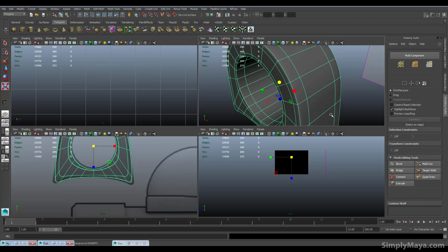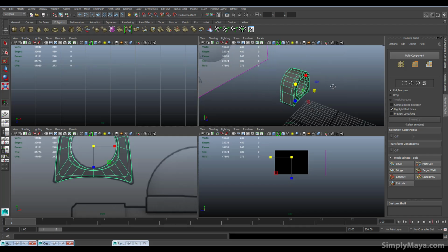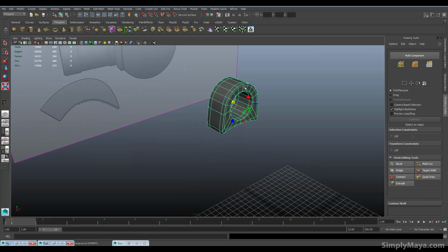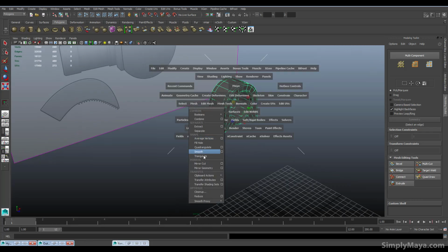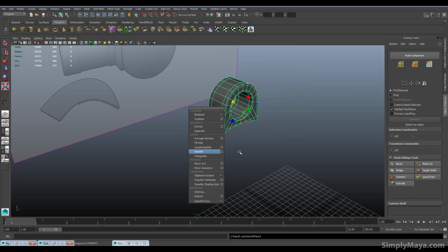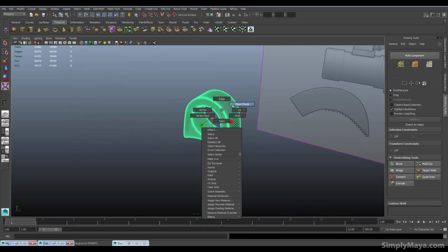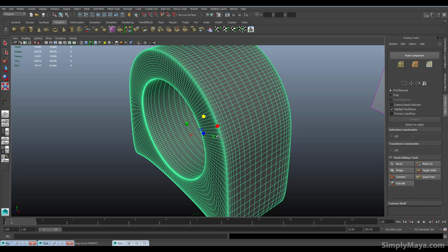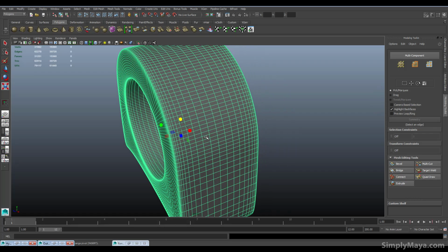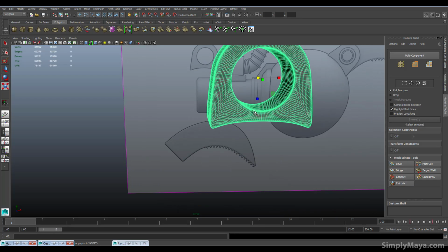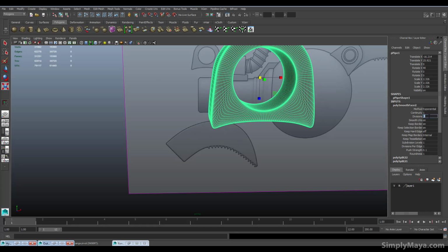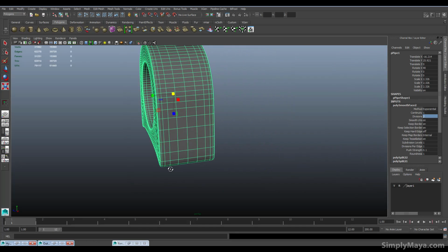And again, we don't quite have the hard chamfer, so we could repurpose this smooth geometry and turn it back into something with a nice chamfered edge. So it is sometimes nice to just be able to go mesh smooth. Let's put this up to a couple of smoothing levels. There we go. That might be a bit too smooth, because that's really high poly now. You can still work with it when it's this high if you want to, but it's a pretty small component, so I'm going to go into the channel box and turn that smooth face divisions down to 2. That's more than enough.